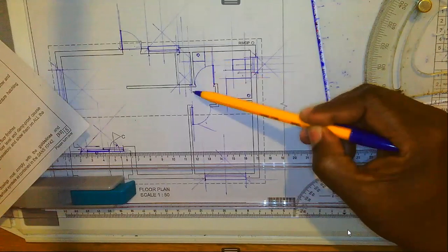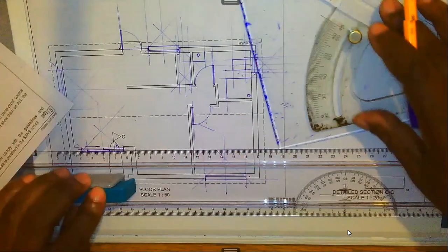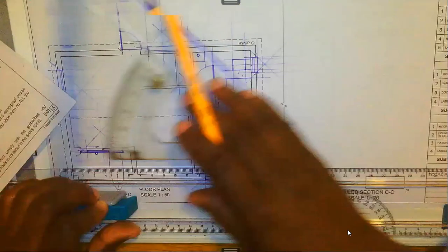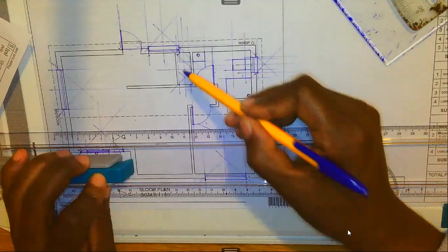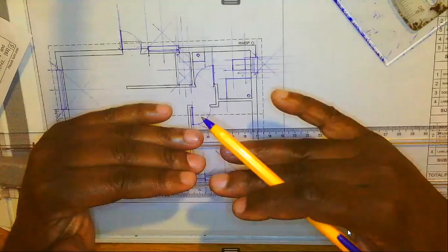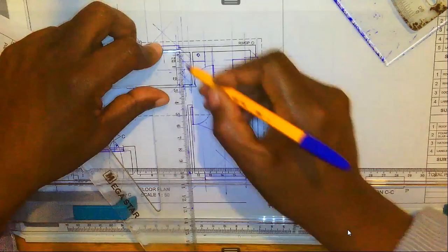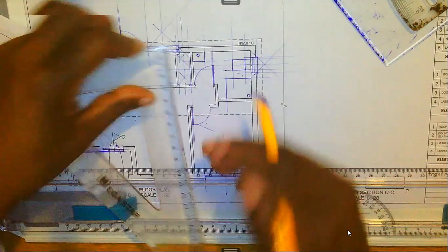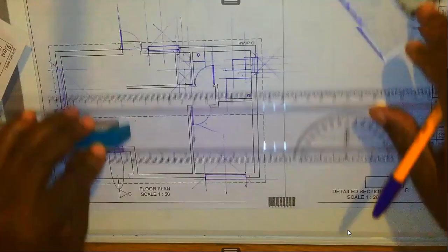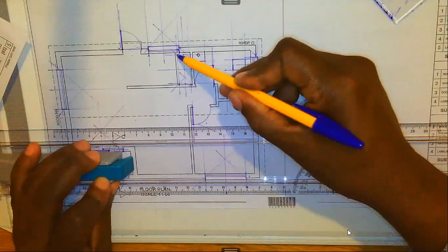So what I want you to do, again, you do the same thing: you miter in order to get the midpoint from this end, and this other miter is already there, then you do this. So this is the midpoint. Either side, we measure 12, 12. So I'm going to measure 12 this side and another 12 this side, which is our 24, like that. So from here to there, that's 24, which is representing 1,200.